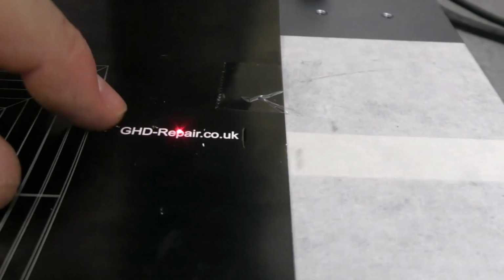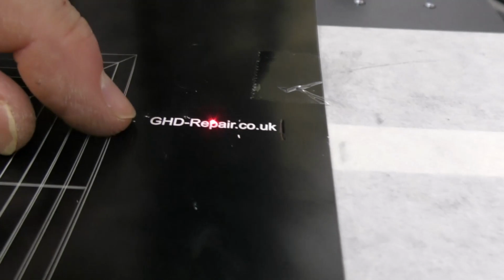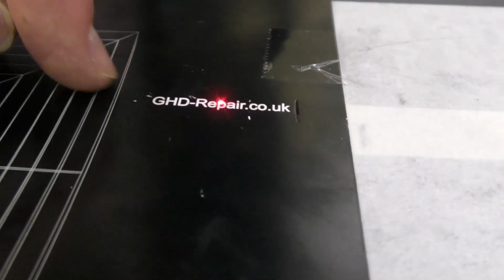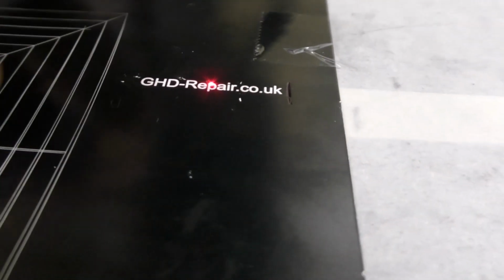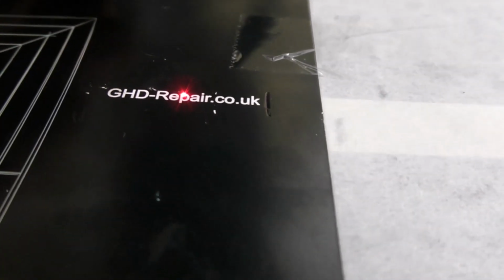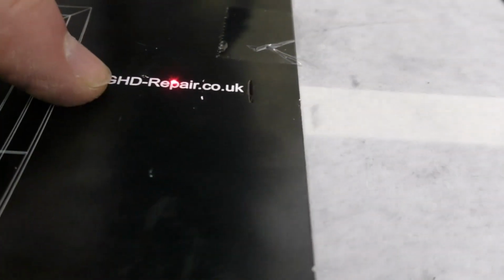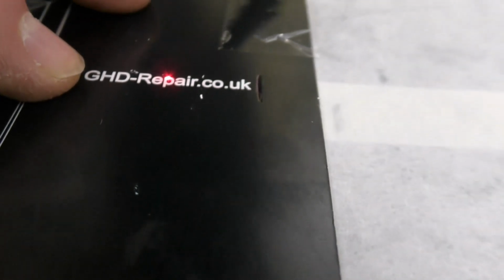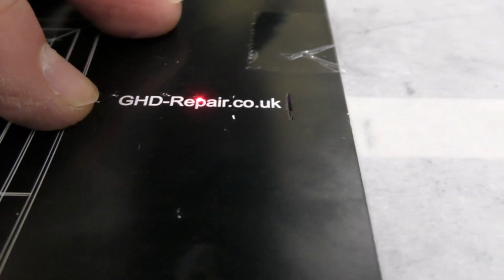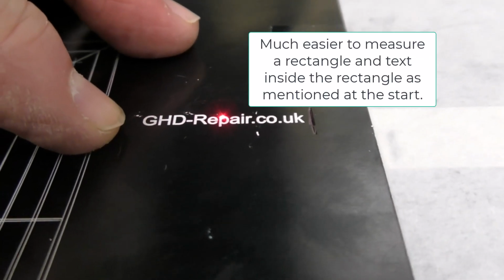Alright, so just adding this one on to the end of that first video on the red tab. I thought I might as well mark that and then just measure it. It's so much easier. The actual X measurement is bang on. It's 30.07 as best as I can measure. The one that is out is the 3.707 height of this. It is a little on the low side, so it may well have to adjust that Y figure